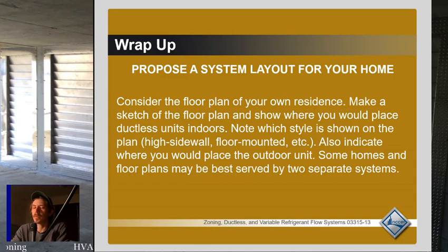You should always do proper load calculations and proper sizing wherever possible where you install a mini split, because if it's constantly operating on too low of a speed, it's going to have trouble controlling humidity. And in a lot of houses where there are a lot of mini splits that are oversized, people experience very significant humidity issues, because since they're variable speed, guys think, oh, it doesn't matter if I oversize it. But it does matter if you oversize them. It matters a lot, because a well-designed system controls humidity very well. An oversized system does not control humidity very well.